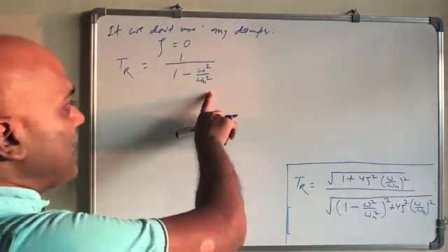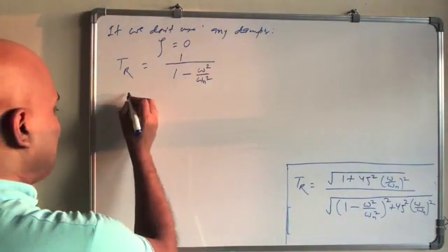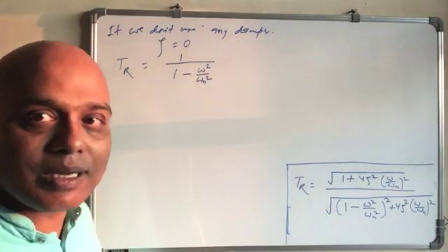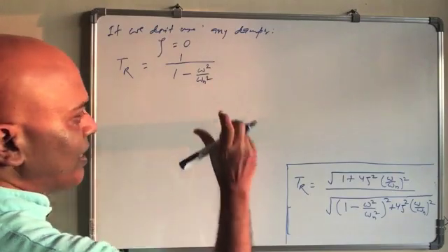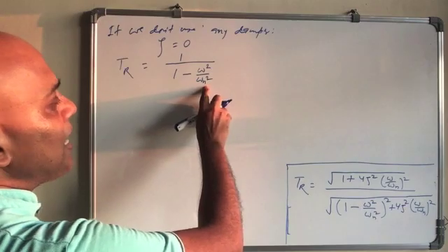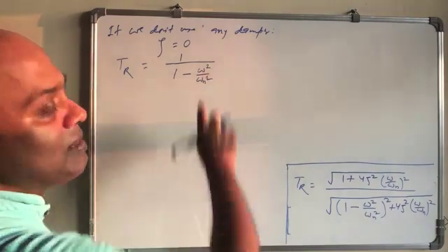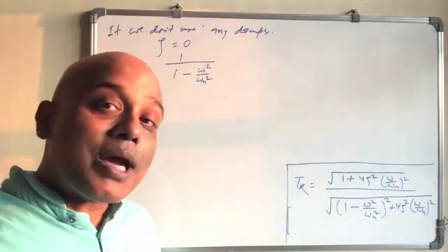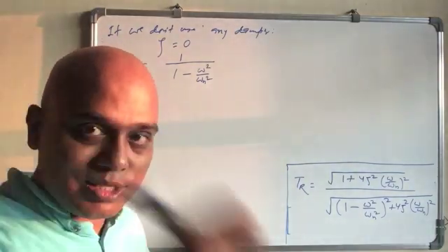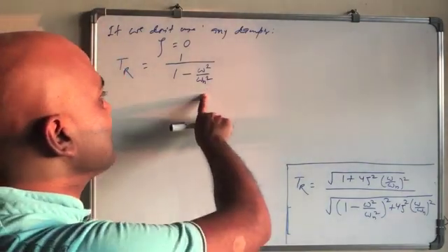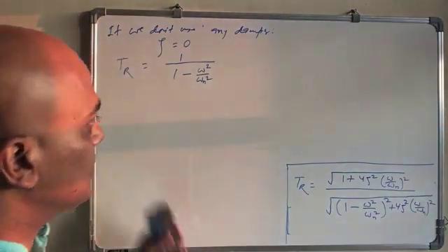Yeah? Hence you design a system such that, let us say if you are just using the spring, then you are going to design the engine in such a way that omega n will not be matching with the omega of the rotation of the unbalanced mass. So you should not match it. If you match it, then there will be very high transmissibility, the transmission of force to the ground. Okay.